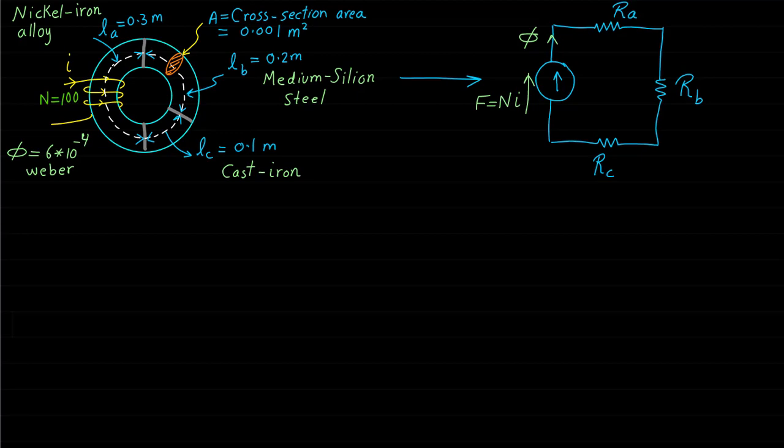Another important note is that the magnetic field lines phi is the same for any series magnetic path in the equivalent magnetic circuit. However, the magnetic field densities B of the series magnetic path are the same only if the cross-section areas of the magnetic path are equal. In other words, if the cross-section areas of the reluctances are different, the magnetic field densities are different as well.